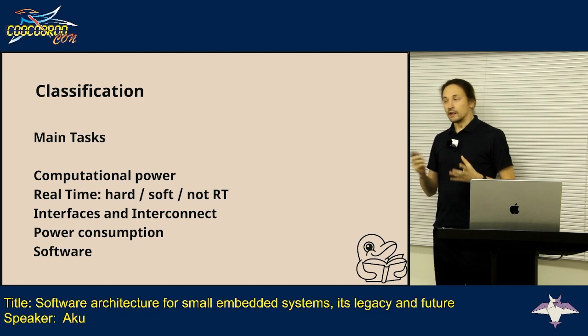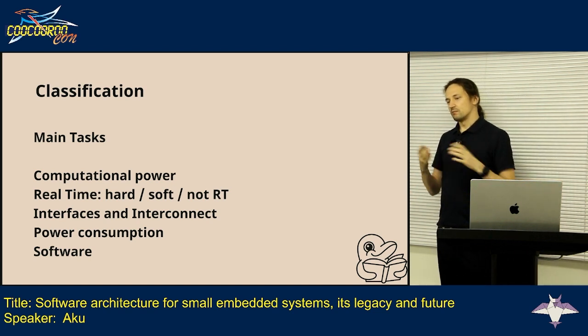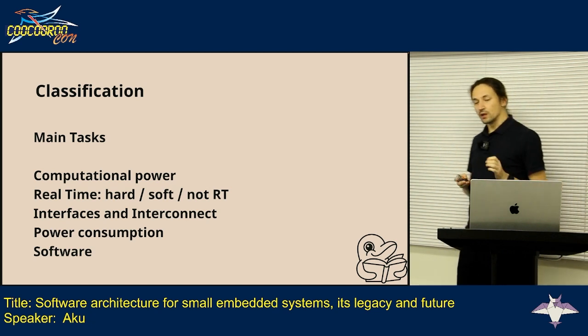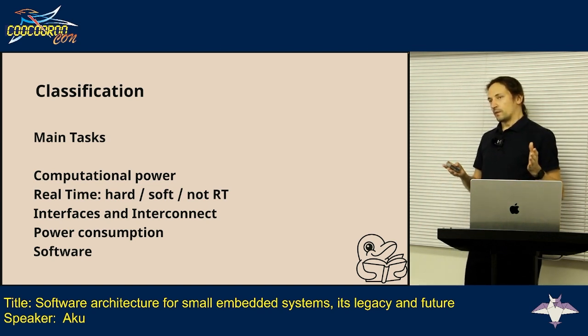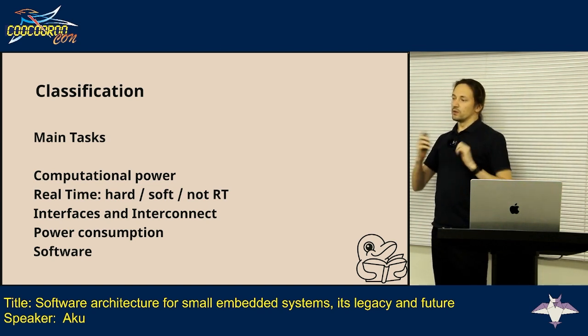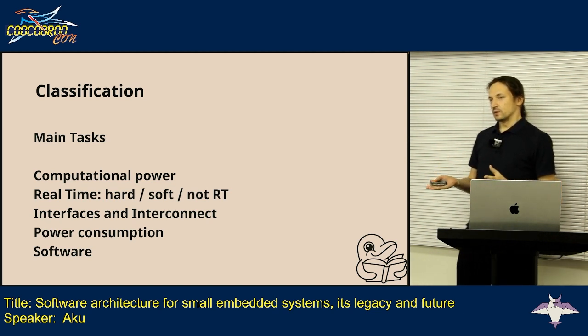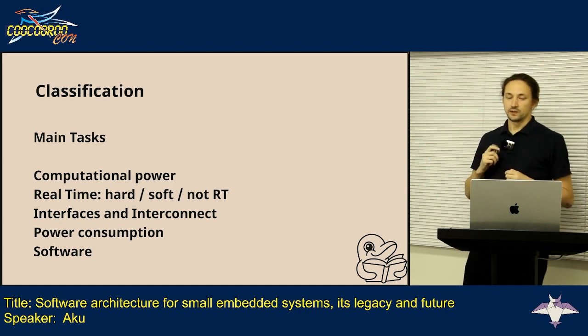Now we have much more complex CPUs with architectures that require some time. If we're talking about modern ARM cores in the M series, you usually need at least 20 clocks before the interrupt is delivered, and in some cases, with big A cores, interrupts can take even longer.